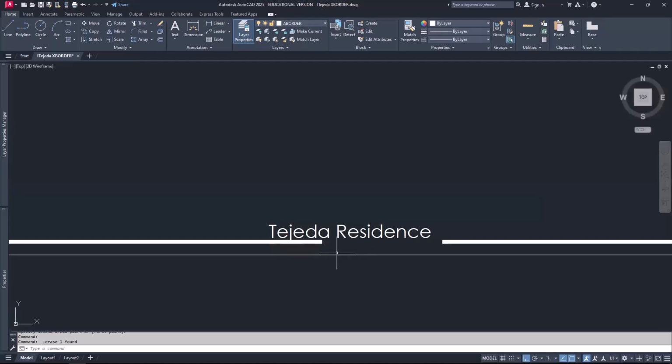It's still a polyline. And now let's see if I can trim. TR, enter. Will this trim out? No, and that's fine. Okay, so I can take this and just bring it over right there. And then I can take my text and maybe just bring it down a little bit to make it fit in between. And if you want to be really, really precise, and I get it, because that's how I am, I'll draw myself a line from the midpoint.